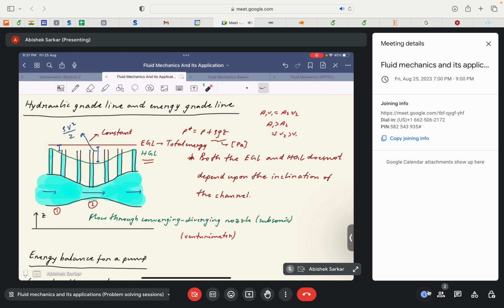So keeping that in mind, considering the Bernoulli equation, P plus rho g z plus rho v square by 2 needs to be constant, so the moment this goes up, this needs to go down, right? Which is clearly being observed here. The dynamic pressure head goes up, so the piezometric pressure goes down.